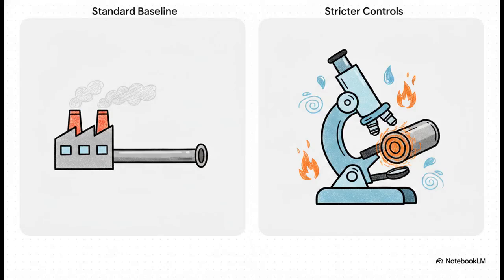So PSL1, that's your standard everyday baseline for line pipe. It lays out acceptable manufacturing processes and standard delivery conditions. But when you crank that dial up to PSL2, you are entering a world of much stricter controls. PSL2 requires mandatory specific delivery conditions, like requiring the steel to be quenched and tempered, and it demands significantly tighter chemical tracking and testing across the board.